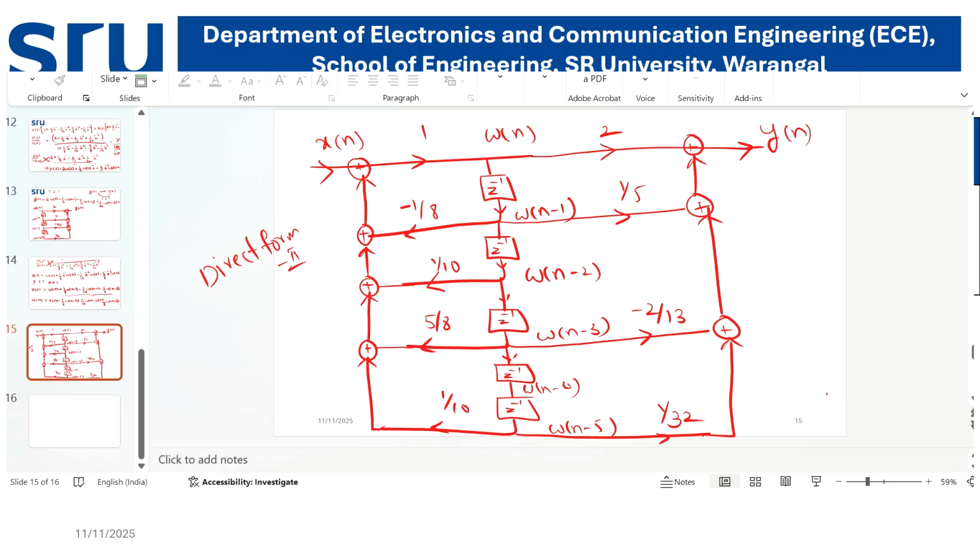Now here for w of n minus 2, we don't have a connection. Similarly for w of n minus 4 also we don't have a connection. Suppose in the given expression, if these terms are also available, then you have to use these terms with one more adder. And coming back to the number of adders required, it is 5 plus 5, that is 10. And the number of memory locations, the formula is maximum of m comma n. The maximum of 5 comma 5 is 5. Alright? So 1, 2, 3, 4 and 5.